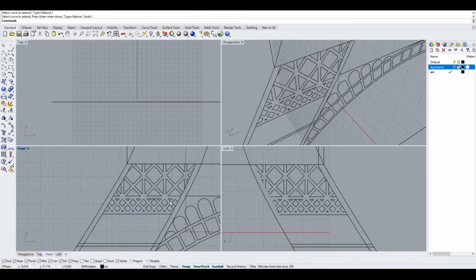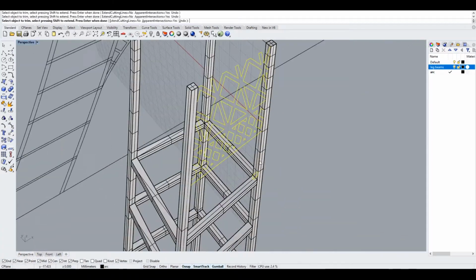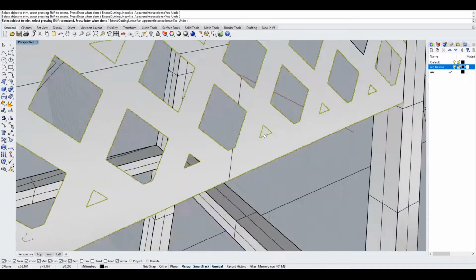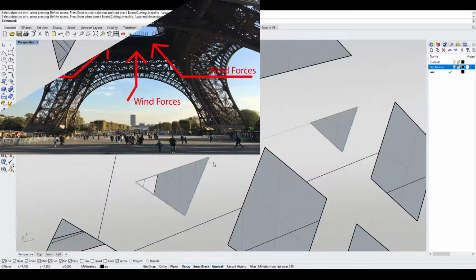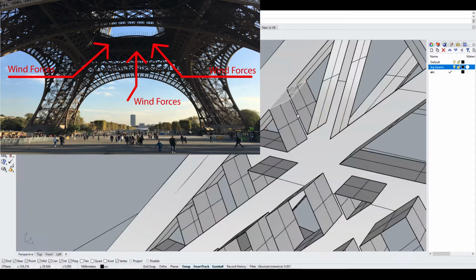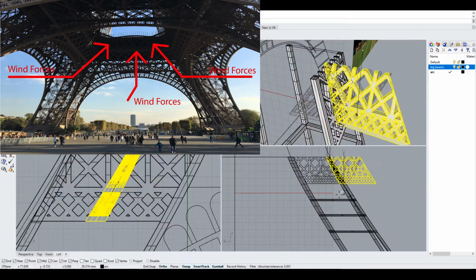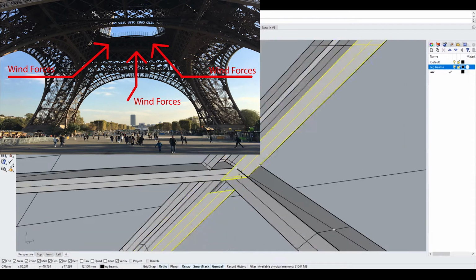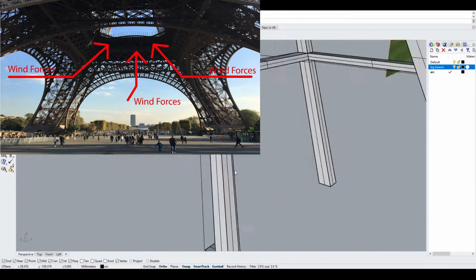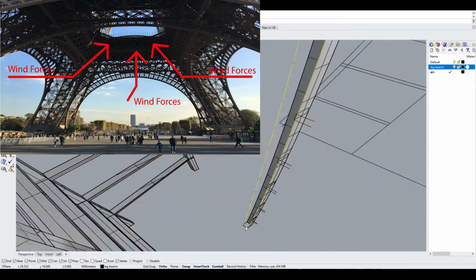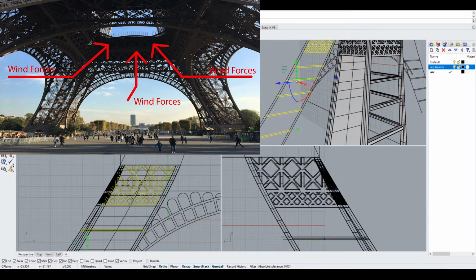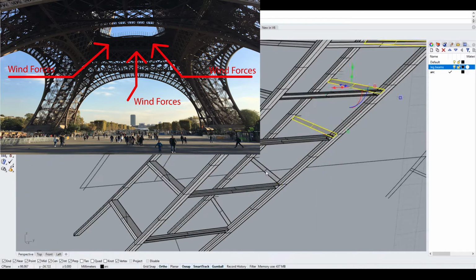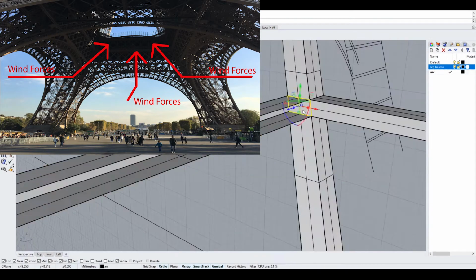The curvature of the uprights is mathematically determined to offer the most efficient wind resistance possible. As Eiffel himself explains, all the cutting force of the wind passes into the interior of the leading edge uprights. Lines drawn tangential to each upright with the point of each tangent at the same height will always intersect at the second point, which is exactly the point through which passes the flow resultant from the action of the wind on that part of the tower support situated above the 2 points in question.